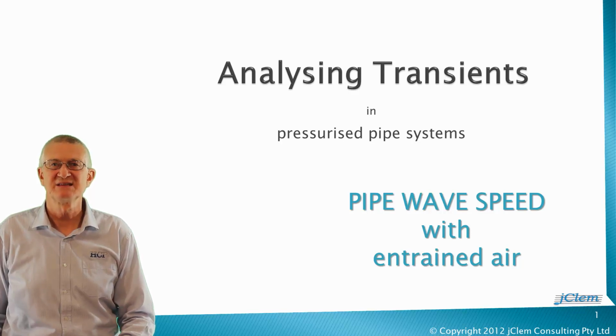It is important to note I am talking about entrained air bubbles, not dissolved air content. We are discussing the significant impact of air bubbles because bubbles act as a set of shock absorbers dispersed throughout the fluid. The concentration of air chemically dissolved into a pipe's fluid does not have this effect on compressive wave speed because dissolved air does not create a set of shock absorbers.